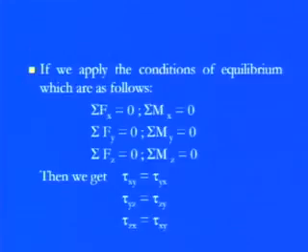you see here the two things are there: one, whatever forces or moments are applied on the object are well set up, the summation of the forces as well as the moments are 0, and we have the unit cube which has a symmetric geometry. So if you apply those conditions, then we can conclude that the shear forces applied in x direction, tau xy, or in y direction, tau yx, mean that what we are doing here is simply changing the direction of force as well as the domain.